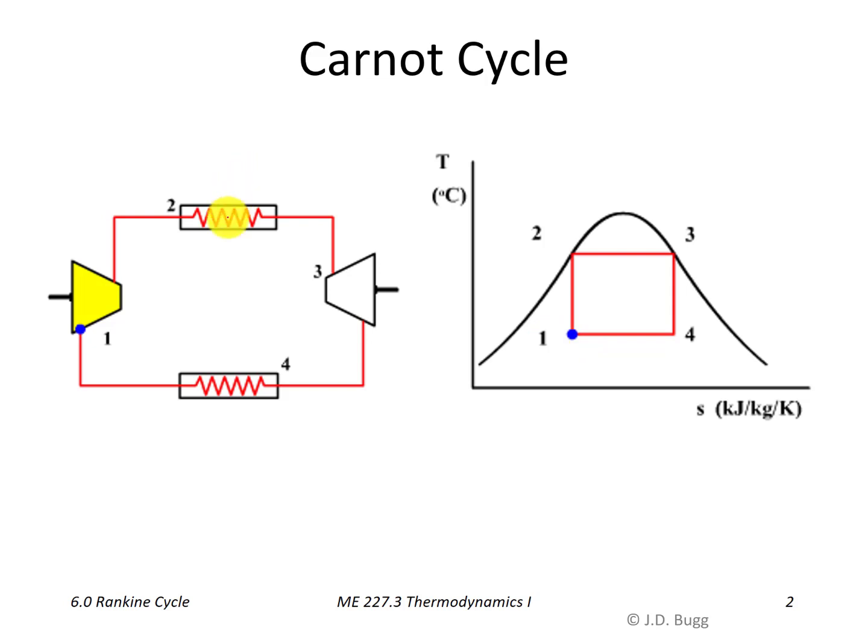So heat is added to the cycle in the boiler, removed from the cycle in the condenser, work is produced by the turbine, and work is consumed by the compressor. So compressor, boiler, turbine, and condenser. Now, just like for the refrigeration system, there were problems operating completely inside the liquid vapor region. This current Carnot cycle has the same problems.